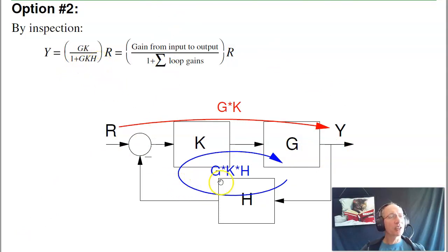That's actually not correct. Take these two blocks and cascade them. What I'll get is this gain squared. And when I square it, I'm going to miss a term. So if you have two systems cascaded, the shortcut that I talked about doesn't work. Instead, solve each one separately, then multiply the two answers together, then you get the right answer.